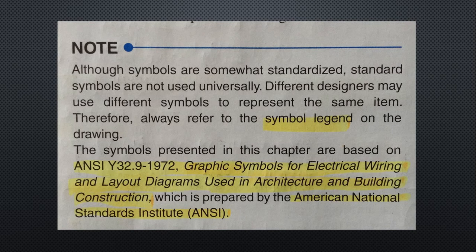Elevations show the side view of an area or object. An elevation is provided when the plan view cannot provide the information clearly. By studying both the plan and elevation for an area, you can visualize the construction in 3 dimensions. In situations where a detail cannot be shown clearly in the plan or in the elevation, a sectional drawing is used.